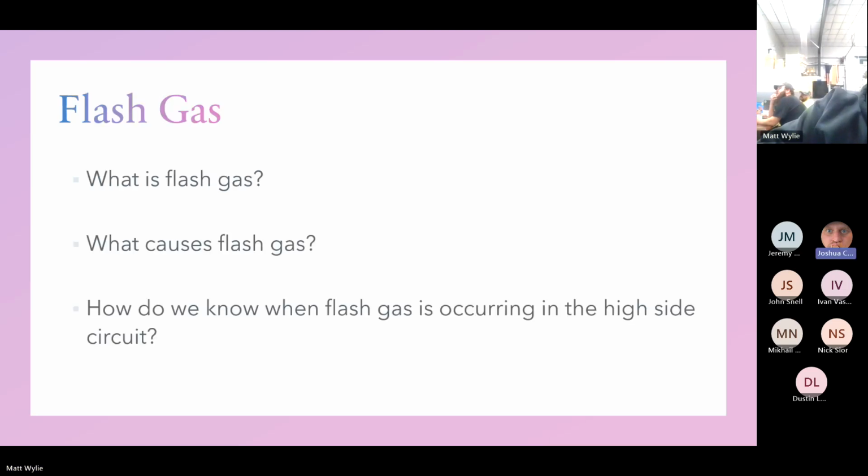I was going to mention too, some of those condensers have split coils. You have to pop the top on those and peel it apart and clean in between, because the dirt gets stuck between the two. It's cottonwood seed. I don't know if this is kosher or not, but just taking a lighter to the bottom of it does a really good job.